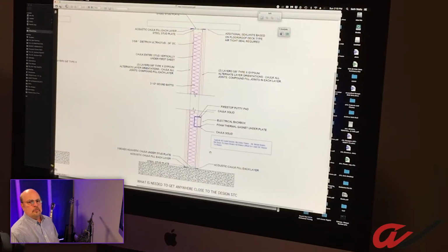Now, one of the things that's really frustrating, ranting again, is the field performance of contractors. Contractors have a funny way of trying to hide things that they don't think you're ever going to see. So we've got a wall that was built recently at a project where it was testing in the 46 range. It was STC 63 design, should have been testing around 58. And we've had these built on other jobs where they work just fine.